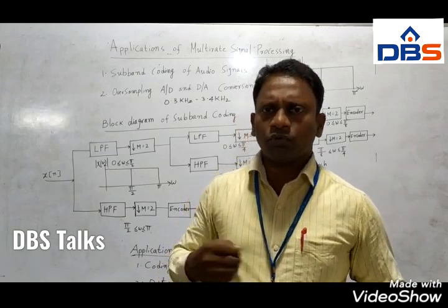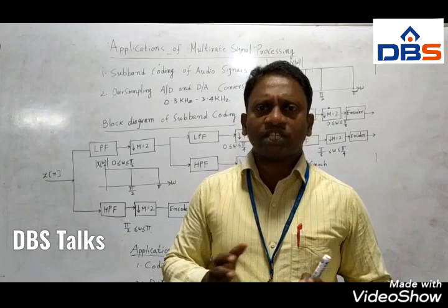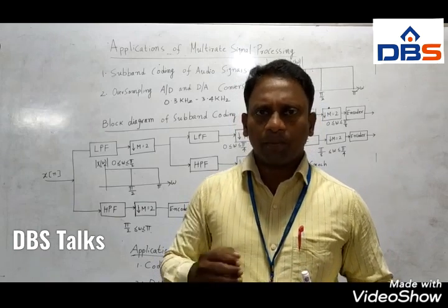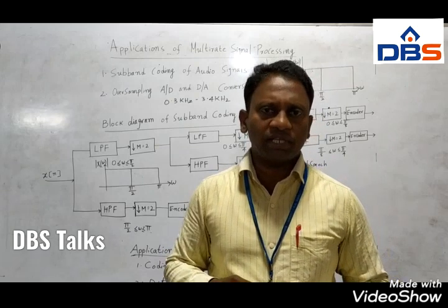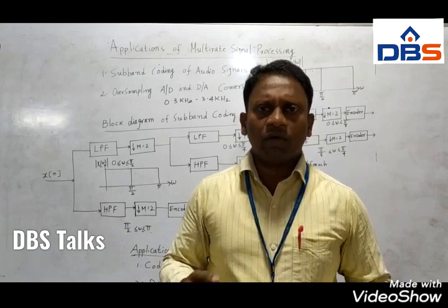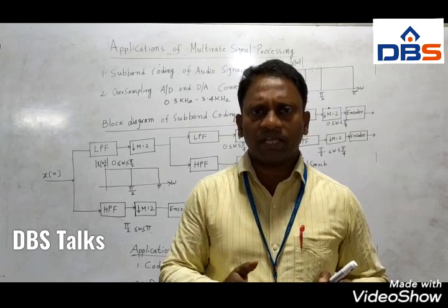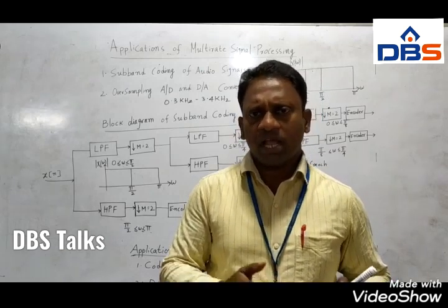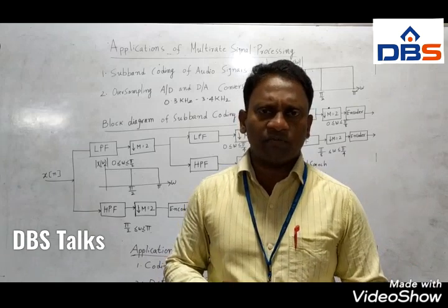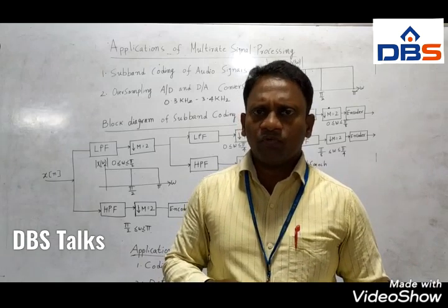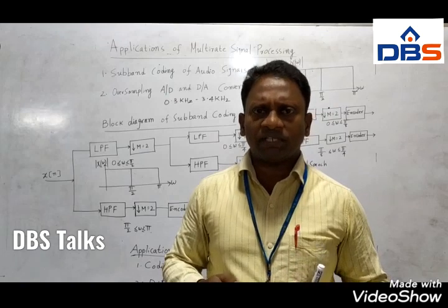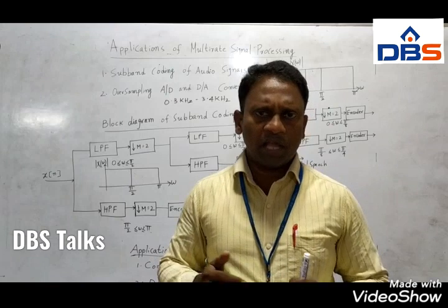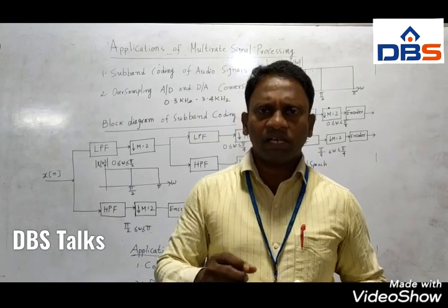So the necessity of subband coding is that we have to code it separately at low frequencies and high frequencies. Most of the energy of the speech is concentrated at the low frequencies and less energy is concentrated at the high frequencies. So we need to represent the low frequency signal with a high number of bits and the high frequency signal with a less number of bits.